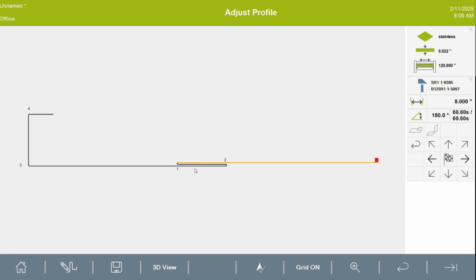But one side of that part has got to be a little more open than the other side because of the lengths. Okay. So you're going to have this side open, let's just say an 1/8 inch, and then the other side is going to have to be a couple of material thicknesses, either more or less than that, for that to nest in properly. Okay. So just keep that in mind. S-locks are doable. Just got to be mindful of opening that hem the right amount on each side so that everything kind of fits in.